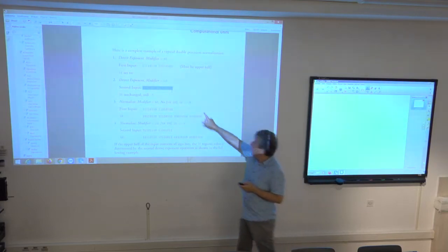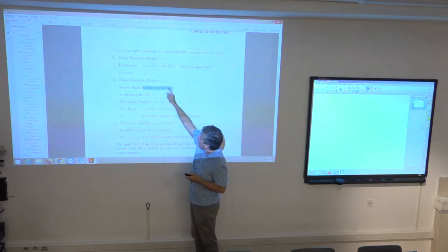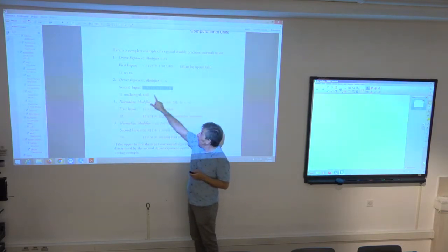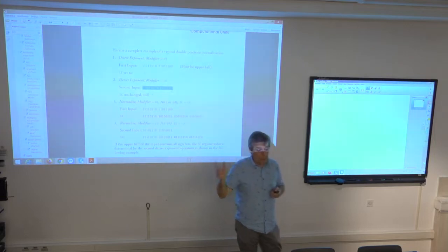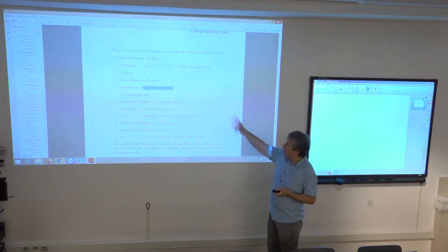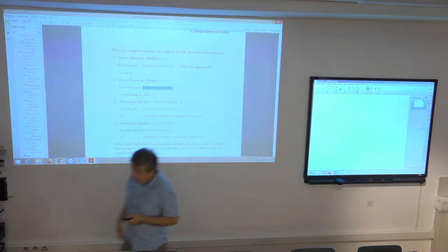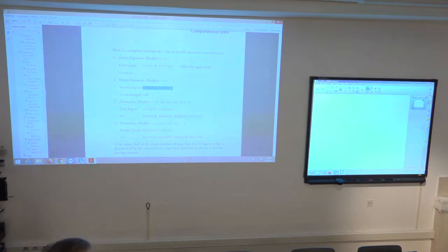But for example, if the upper word would be all ones, that would mean that the leading one is somewhere in the lower word. And by applying this second exponent instruction, but relatively low to the lower word, you will simply get the actual value, which is -17, for example. Because the leading one is in the lower word, not in the upper word, but on the 17th position of this 32-bit value. So by combining these 2 exponent instructions for the upper word and lower word, you get the final exponent of the input 32-bit value with only 2 assembly instructions.